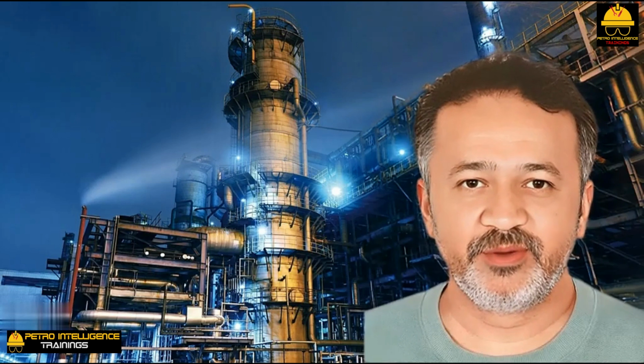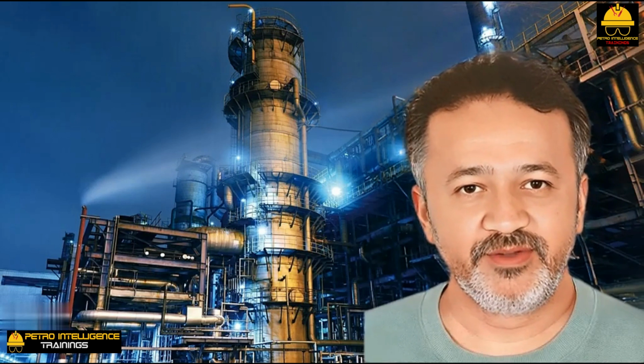Condensation in shell and tube heat exchangers. If what you have just listened to seems to be a repetition of the discussion of steam reboilers in my previous video, your analysis is correct. A steam reboiler has the same problems and works on the same principles as a process condenser. The only difference is that a steam reboiler's heat is removed by the shell side process fluid, and a process condenser's heat is removed by cooling water or air.